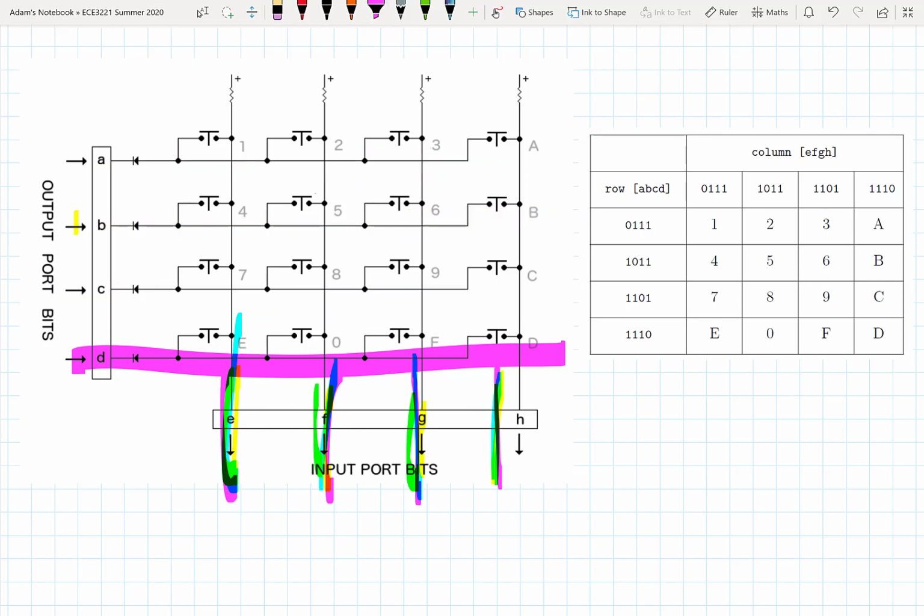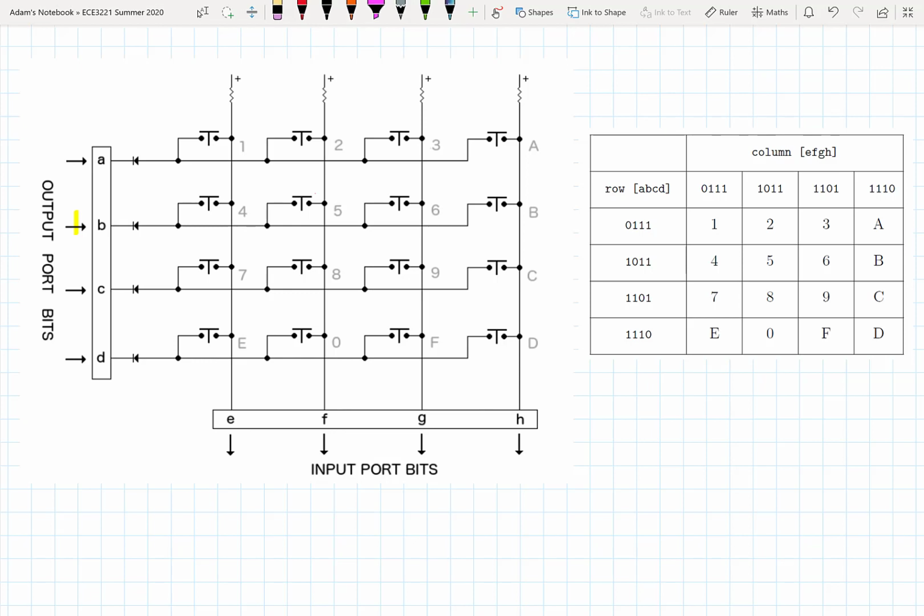One thing we should also remind ourselves of is that these are physical buttons we're talking about, so we still do have to be concerned with switch bounce, and either use a hardware interface to counteract that switch bounce or come up with a software solution. Thinking about a software solution, I will remind you that might add quite a substantial delay if we have to add a software delay in with every read of our input port. So it's just something to consider if we have a large keyboard array and we want to ensure that we can scan it quickly.